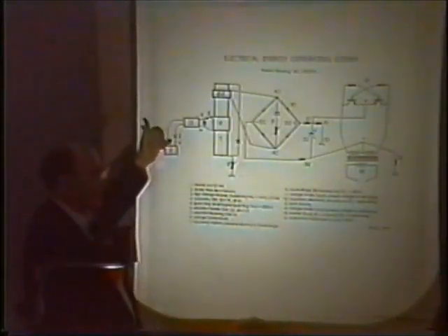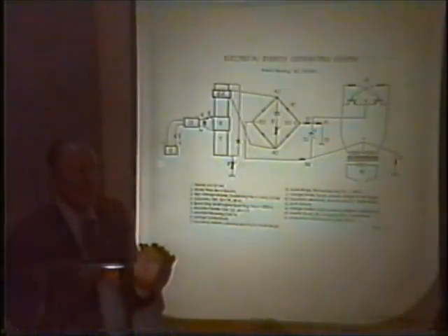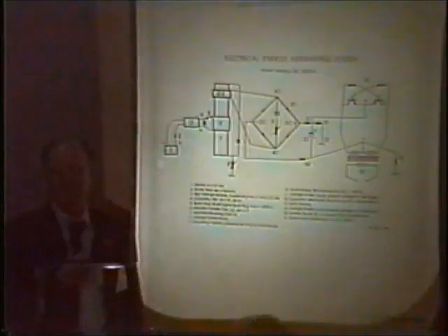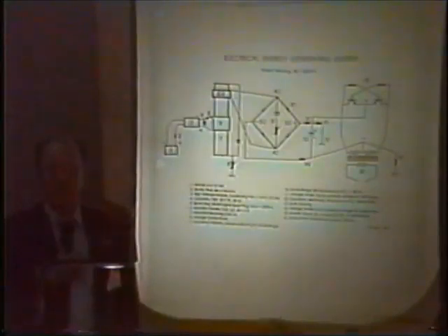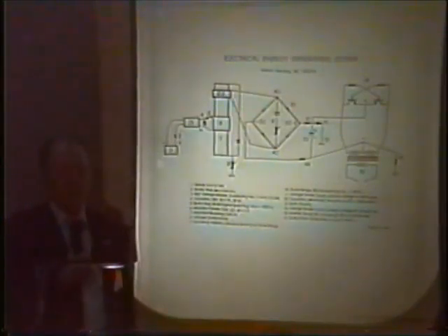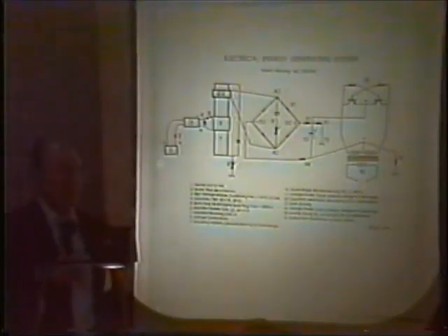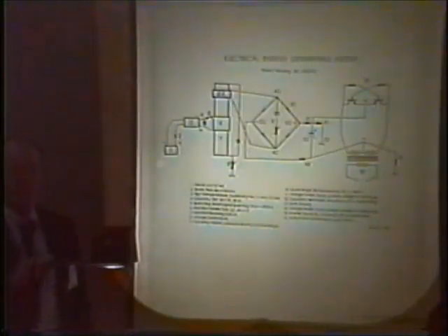Here's a diode that you put on your plus side so that you don't get a kickback. If you get a kickback, it damages your high voltage module. The high voltage module is a laser high voltage source like you'd have in your laser printer or whatever. They're available off the shelf, and if you buy them direct, they're a couple $100 or $300 maybe. If you're lucky enough to find one in an electronic surplus place, it might be as low as $50 or maybe even lower. So needless to say, I've got pretty good at finding the surplus ones.